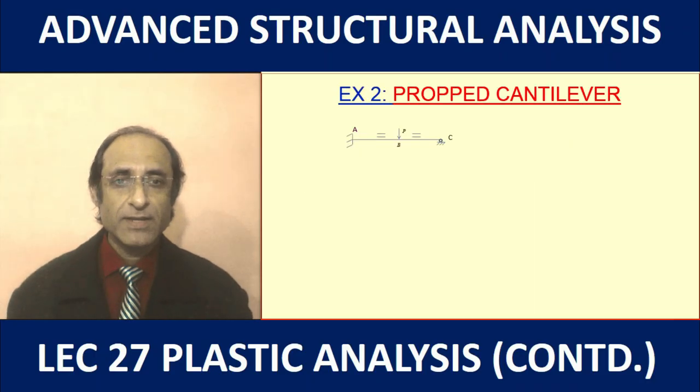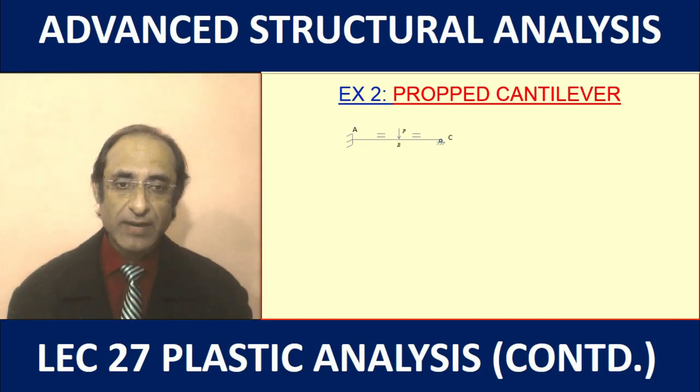same structure. Let us consider another example, an indeterminate structure, a propped cantilever. For this particular structure, the degree of static indeterminacy is 1. That means it would need the development of 2 plastic hinges for the complete collapse to happen. So we are increasing the loads gradually. At the beginning, the applied point load is less than the ultimate load. The deflection pattern will be like this.